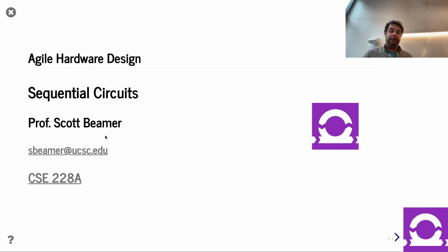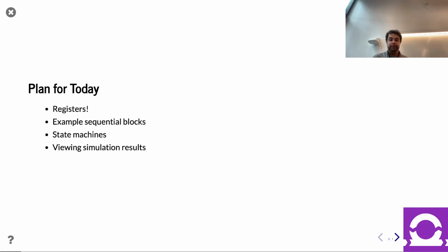And this is going to wrap up our crash course on Chisel, where after today, you're able to make Chisel components that have combinational logic and registers that make sequential logic. You can instantiate modules, etc. So basically, most things you can do in Verilog, you could effectively now do in Chisel. And even though we're just starting out with this basic stuff, there's already some niceties in terms of types or parameterization you're starting to see. The coming lectures will get more in depth into the parameters and the cool things we can do.